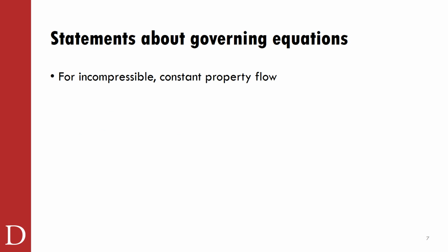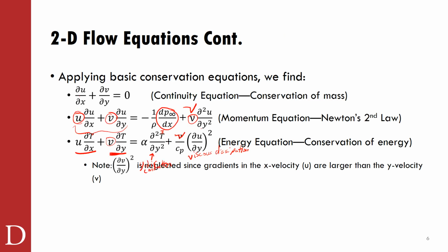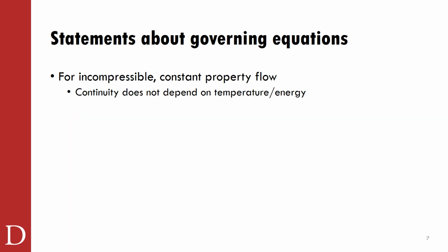So looking at those equations, back for a second, these guys, our continuity equation, this one here, our momentum equation, and our energy equation. What do we see? We see that continuity doesn't have any temperature or energy terms in it. It's just du/dx plus dv/dy is 0.